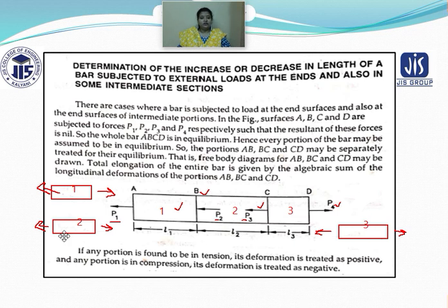So you do not need to write that minus symbol. You do not need to write the negative load there. You only have to consider that negative means it is a compressive load. So in case of 2, you will observe the load is in the reverse, opposite direction, in compressive mode. Here you have obtained tensile, that's why you have given positive. But if you have obtained a negative load result, then in this particular situation you have to provide a compressive load. No negative symbol will be included.